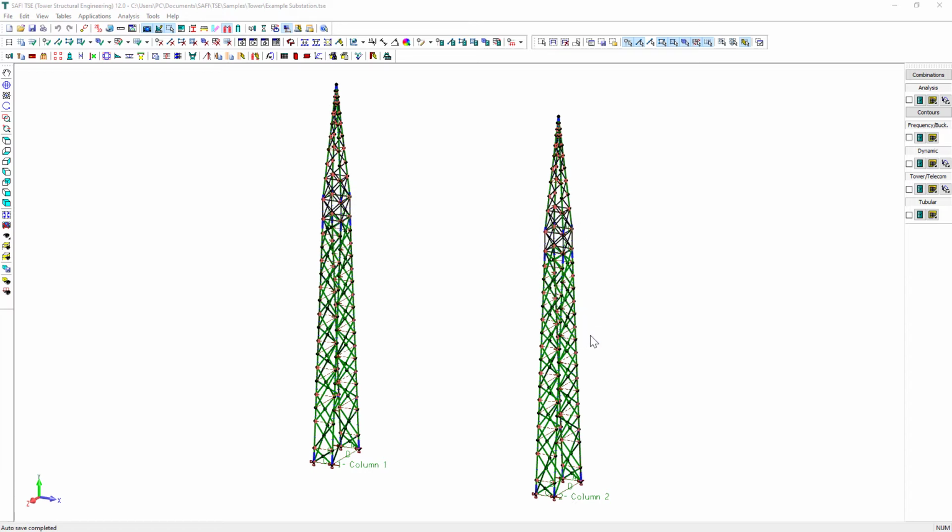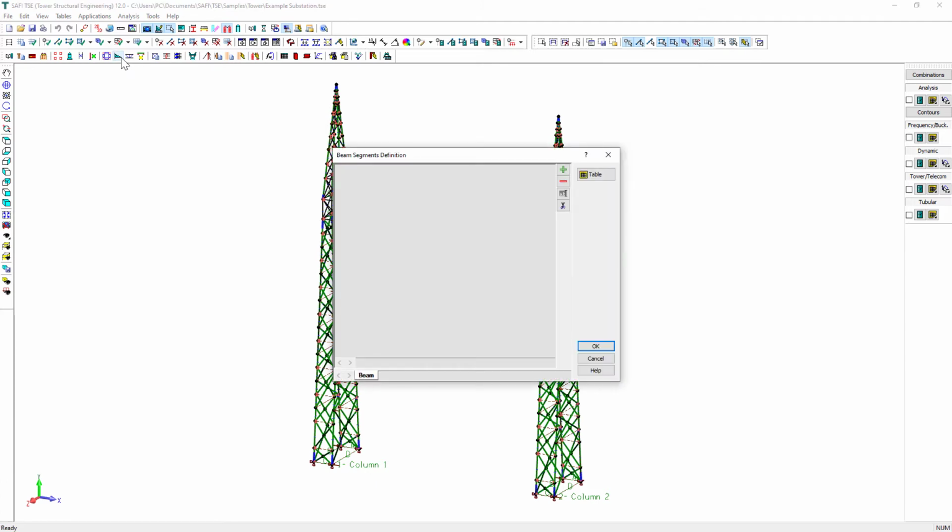Once the beam is identified, we can specify its dimensions. The beam shape is determined using several trapezoidal segments which, combined, will form the beam. The same method is used for beams and columns. In this example, the beam can be represented by a single segment of constant dimensions.